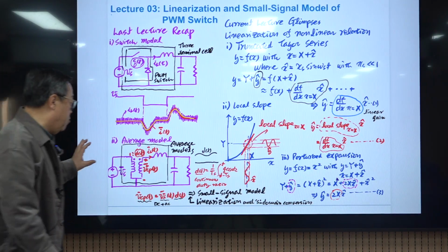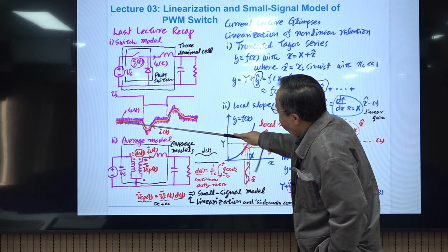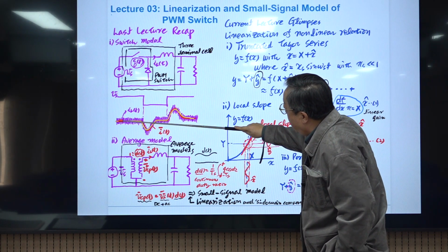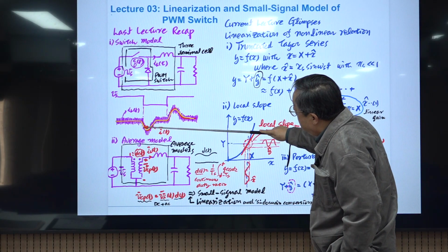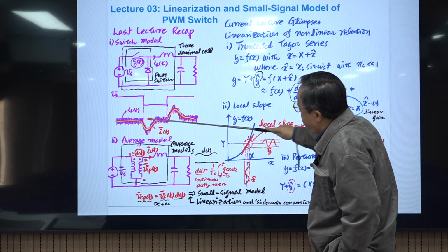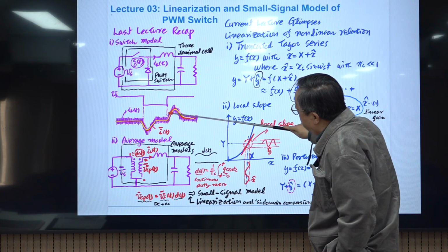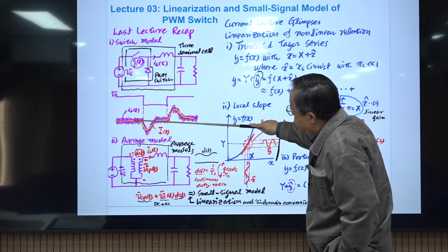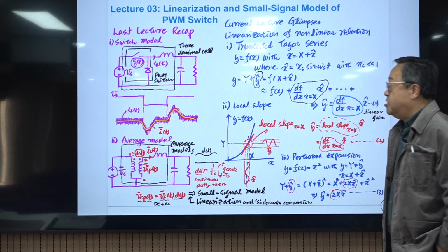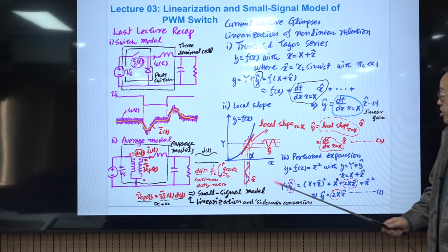Okay, so by simulating this, we obtain this yellow curve. The yellow curve exactly follows the envelope, or time average value, of this purple waveform, which is the cycle by cycle simulation with the triangular ripple component, and this generates the smooth waveform following the average value. Okay, this is the meaning of the average value, the average model of anything.